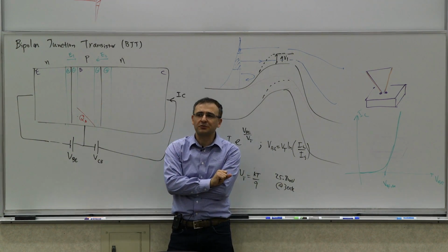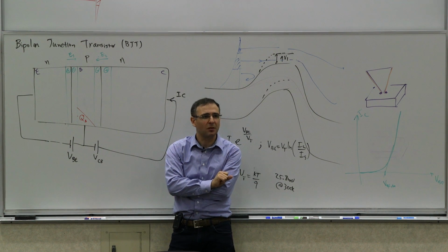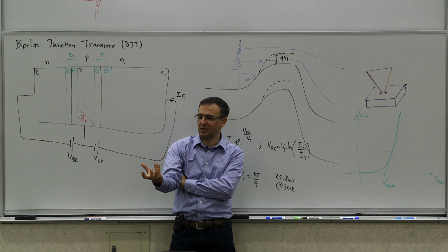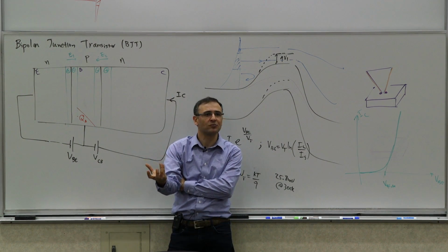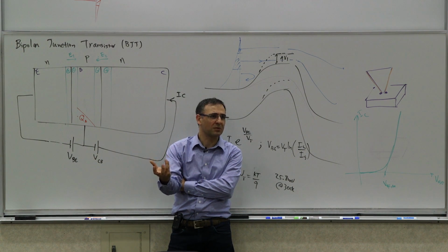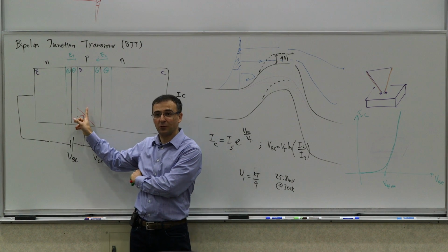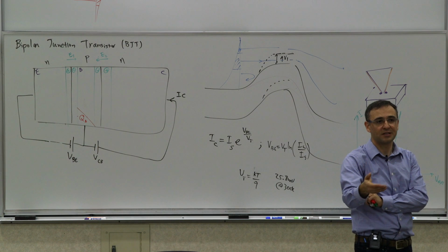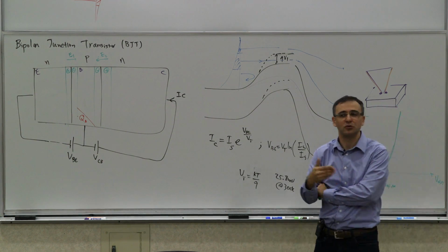So how do you increase p? How do you increase the number of holes in the design for a piece of semiconductor? If I want to get more p's at room temperature, what do I do? What gives more holes per cubic centimeter or per cubic meter of it? More dopants, right? Which basically goes back to what we did already. So as you increase it, that's helpful. That's another reason you increase the doping concentration when you do scaling.